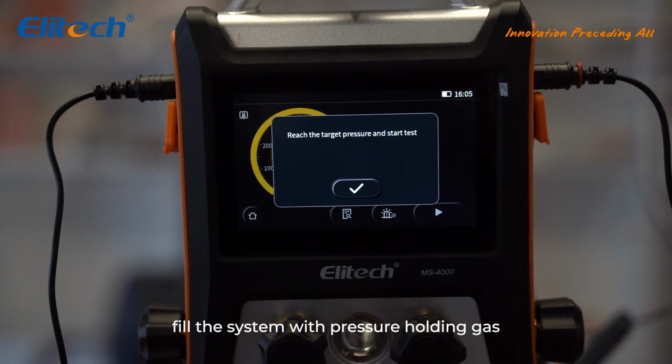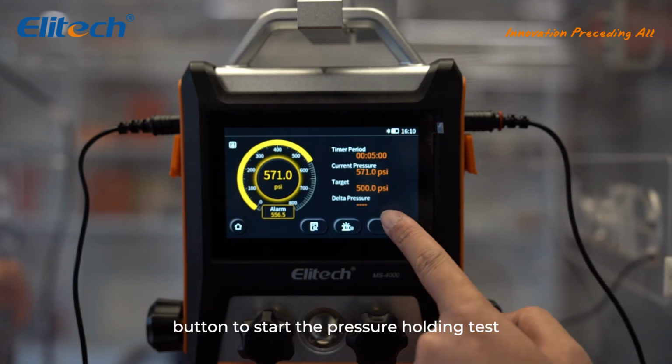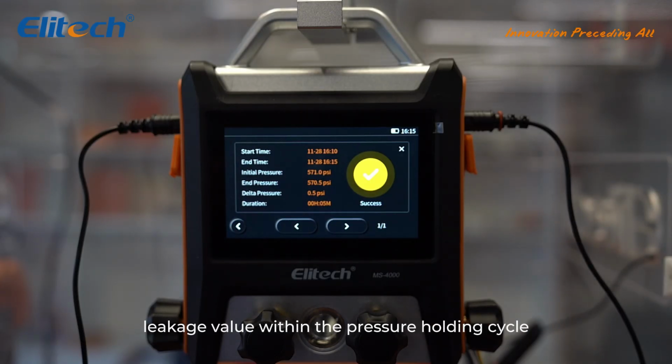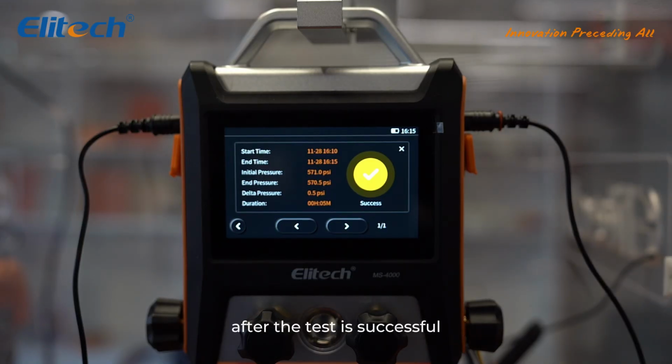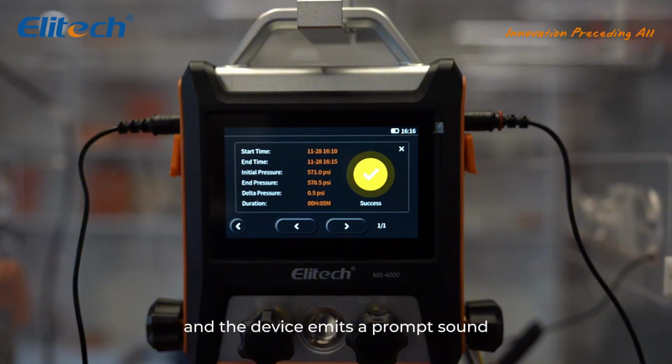Fill the system with pressure holding gas. When the pressurization target value is reached, a pop-up window will prompt on the product. Start pressure holding. Click the Start button to start the pressure holding test. If the current pressure does not exceed the leakage value within the pressure holding cycle, the pressure holding is judged to be successful. After the test is successful, it jumps to the success result display interface, and the device emits